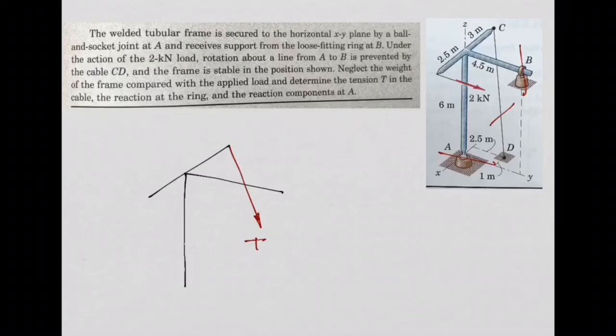That's what we have been doing so far. When we separate the frames of the structure from the supports, we replace the supports with reactions. For a cable, it's the same thing. I'm separating my structure from the cable, I'm cutting the cable, so I need to replace the cable with the reaction on the cable, which is the force on the cable, okay? Which is also always a tension force, not a compressive force. Cables, they only carry tension forces, okay?